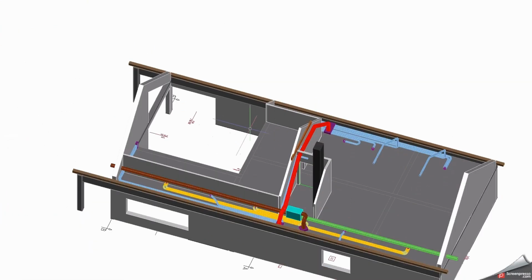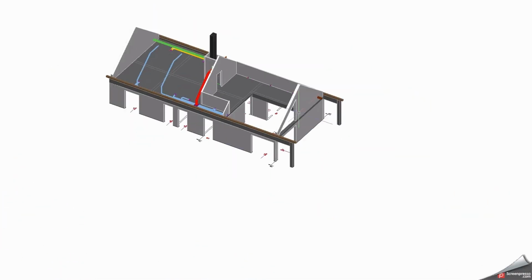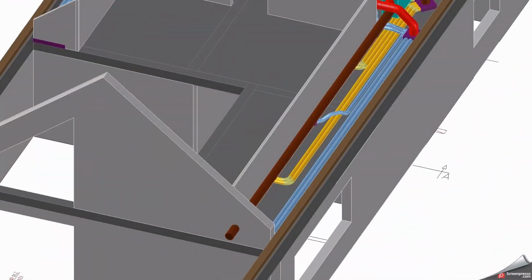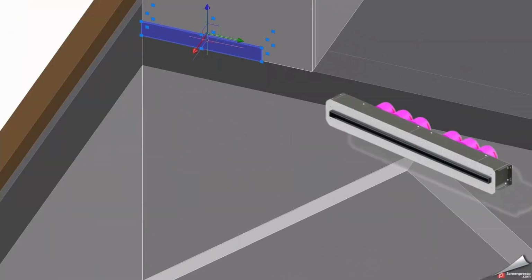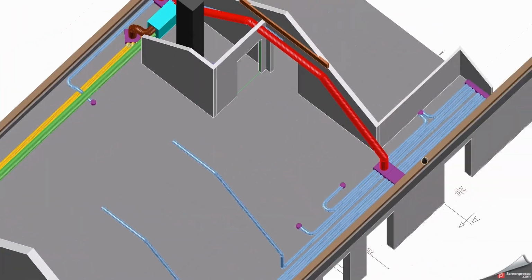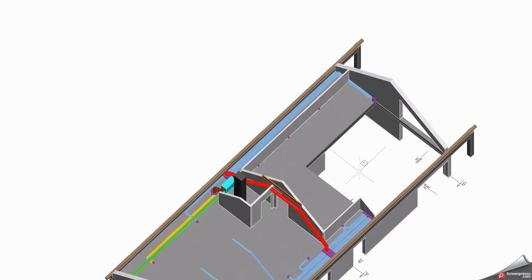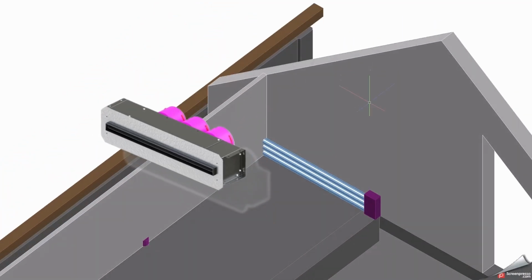The largest room in the house is the living room, with a high cathedral ceiling connected to the kitchen and a study on the mezzanine. It makes up about 30% of the entire building's volume. To ensure proper ventilation in the living room, I decided on aesthetic linear diffusers, one designed for 6 ducts and the other for 3. This smaller diffuser is strategically located near the future steel chimney of the wood-burning stove.